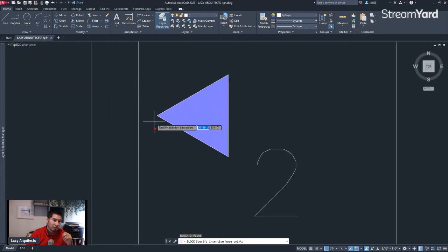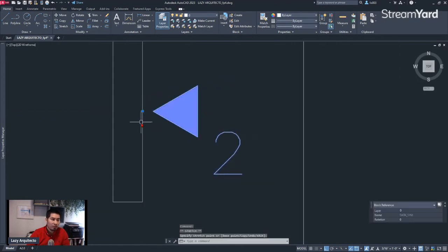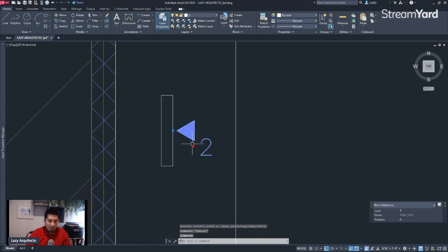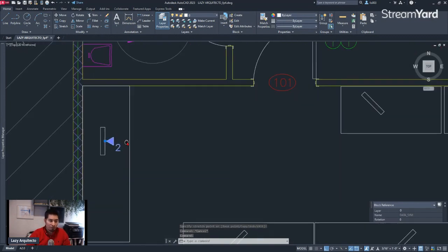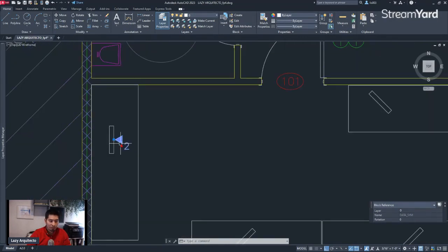That point was not over here on this block, but a little bit over here, because he had to leave a space or a gap between the data symbols. So it would be something around here like so. That way when we placed the block, he could simply place it like that and still have a space over here. So that's one of the first things that we did, of course, to simplify my client's life: convert these symbols into a block.